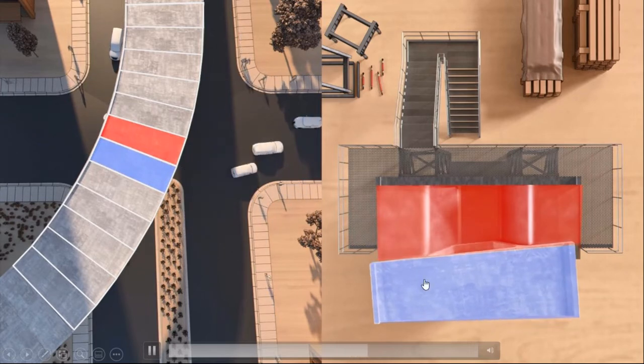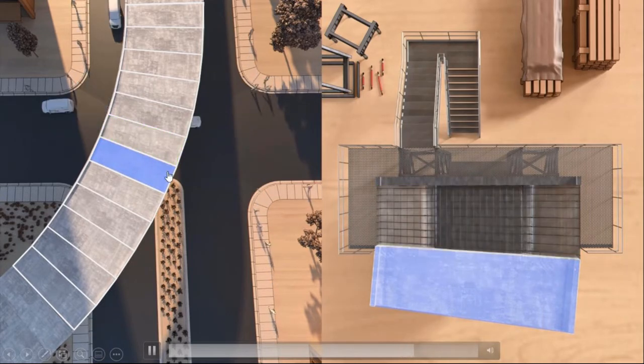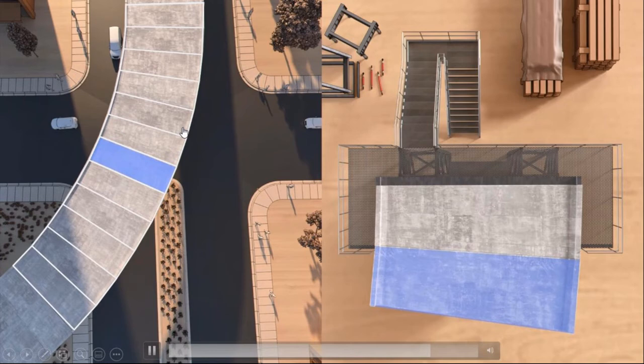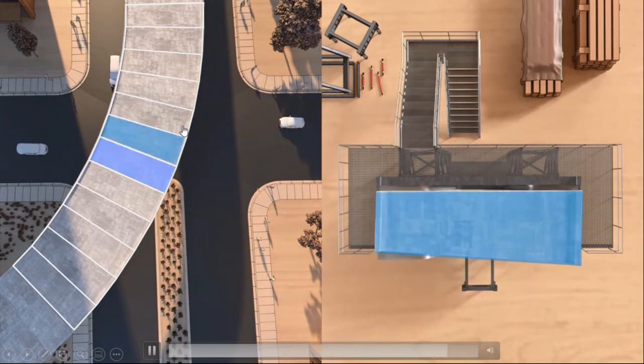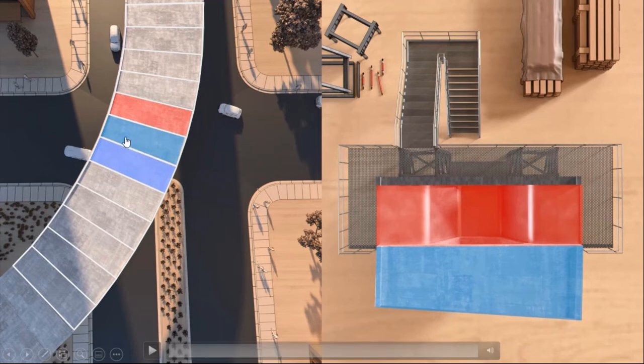So the blue one you adjust back and forth until its shape relative to the form matches what you want in the field. That was what that green light was supposed to indicate. Once you do, you cast it, you move that segment out, and you repeat the process, maintaining the relationship between those two segments. The exact same logic that you saw there in plan view, sort of adjusting the match cast segment back and forth so that you have the right wedge shape. That's exactly what you do for a vertical curve. That's what you do for a twist if you have a change in crossfall from one segment to the next.